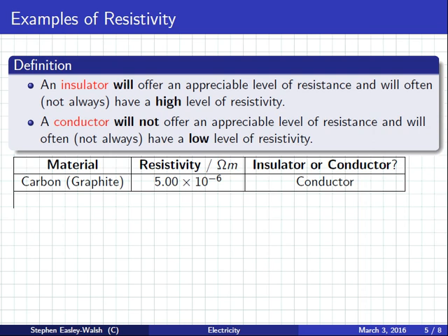So what will happen is when your battery's getting old, the voltage will be less than what it says on the package. So this is 3.7. I expect to see 3.6 or 3.7. When the battery's getting old, it might only say 3.4 or 3.5. So it's a way you can check the health of your batteries to see if it needs replacing.